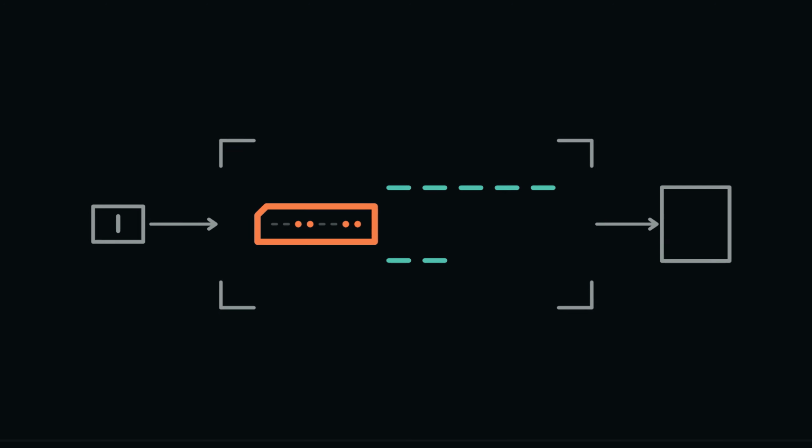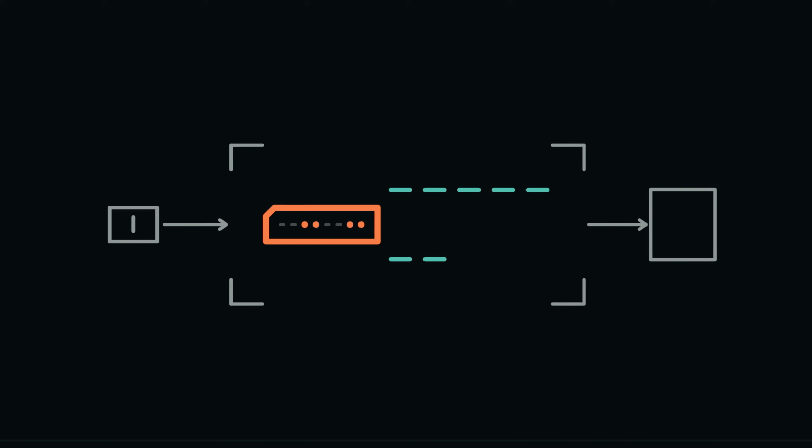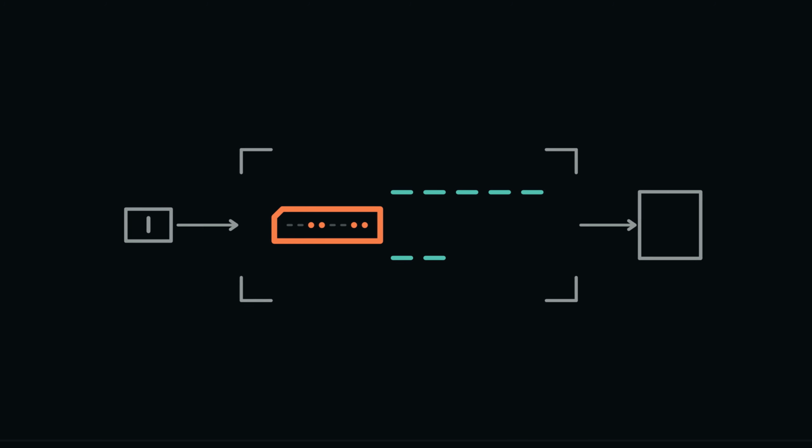See the entire countdown before following one path. At hexadecimal 20, subtract 1 from R0. At 22, compare R0 with 0. At 24, branch to address 28 if the 0 flag is set. At 26, jump back to 20. At 28, halt. R0 begins at 3. The program will produce 2, 1, then 0, and halt.